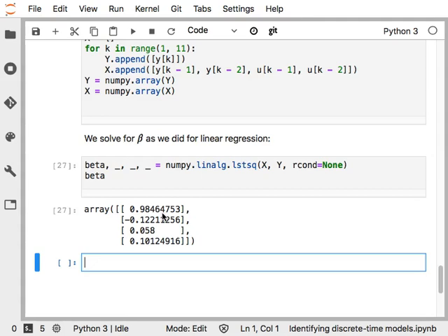This is what modern engineers typically mean when they talk about step testing. When they say they're going to step test the plant, they don't mean they're going to make actual steps. They mean they're going to hook it up to a tool like this, and the best ones can do this fitting incrementally. It can start, do a couple of fits, estimate the certainty in those parameters, and then stop once it's sure enough, which means you spend less time fitting, cause less disruption, and get better results.